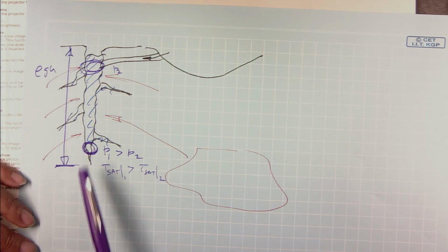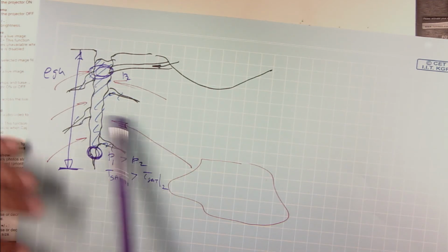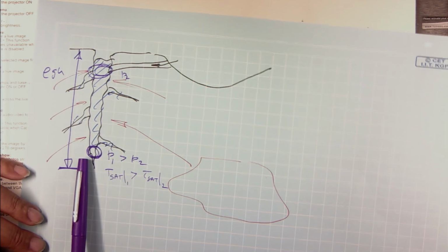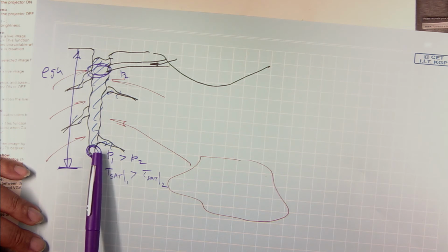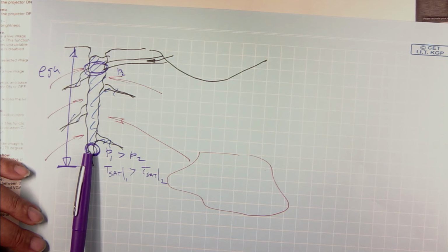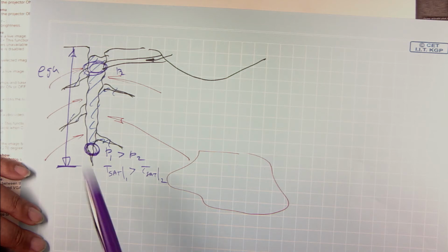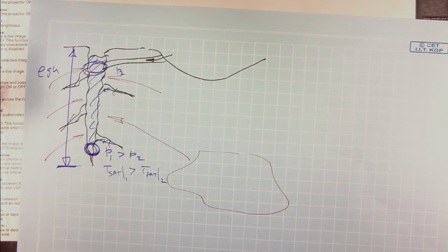Okay? But the moment you nucleate vapor bubbles in this bottom portion over here, the average density here has changed, and the moment nucleation happens here, average density changes, average pressure changes, and all of a sudden the Tsat drops. So now your boiling point, instead of being 110 degrees, has become 105, and the rock around it is probably at 115 or 120 at that point, and now you are very close to critical heat flux all of a sudden. And so then all of a sudden a massive amount of water spontaneously becomes vapor.